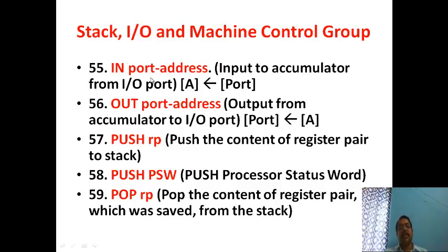So that 8-bit address will have a value, and from that value if you want to bring in a value, then you use an instruction called IN. Similarly, if a value should be moved to an 8-bit address, we use OUT. Now please listen, there is a special instruction called PUSH and POP. Push, you are pushing something to some location. Pop, you are bringing it out, like popcorn coming out of the machine.